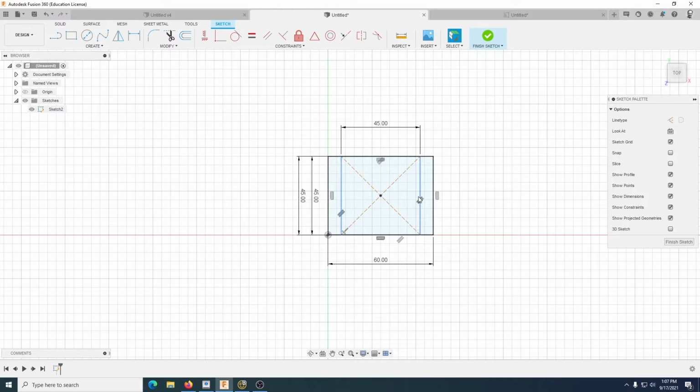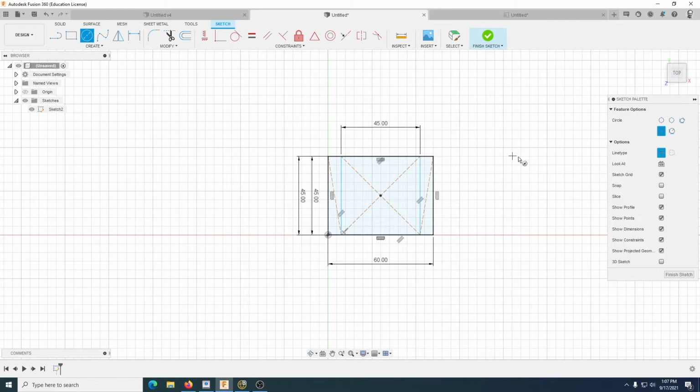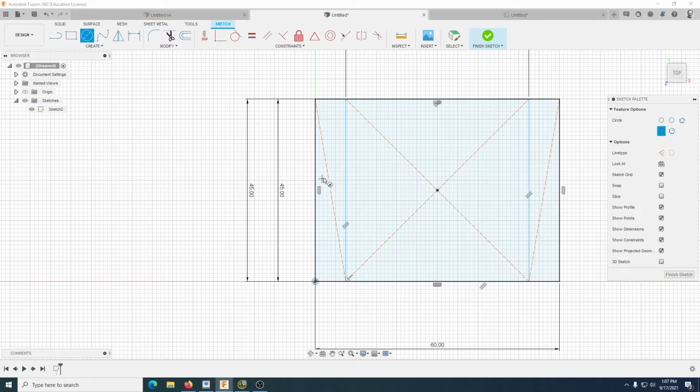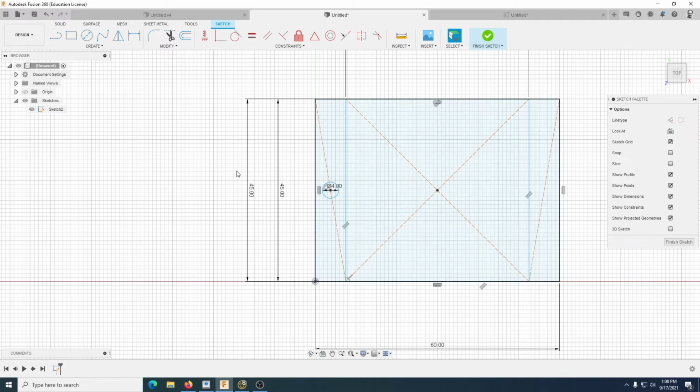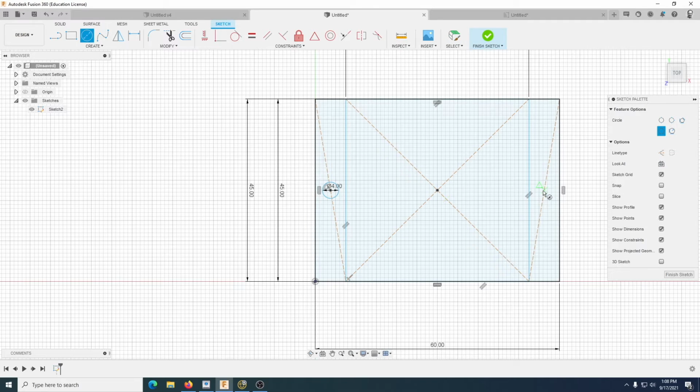Now this here would be flat and would need the holes to secure. Now this time we are going to use the line, and we're going to use construction, and we're just going to go here, and we're just going to go there. And what we'll do now is that center of that line and that center where you see the triangle of that line will actually be the center of from there to there, and of course from there to there. So let's turn off our construction lines and we'll zoom in a bit. Click that, and that is a 4mm diameter hole. And we'll press C for circle again. That's a shortcut key, and we'll just type in 4 there.